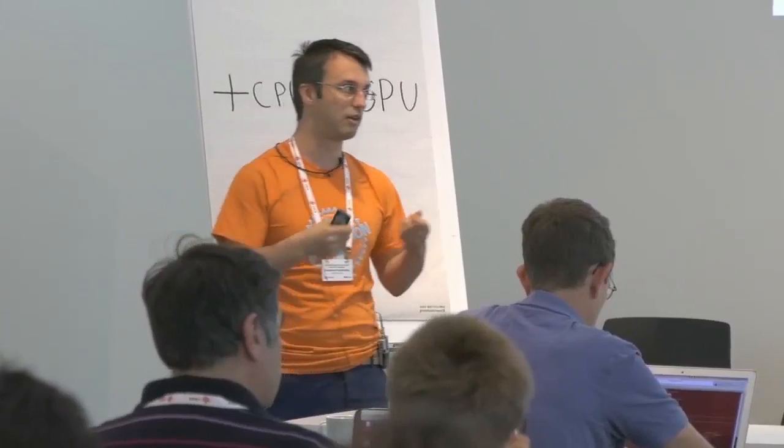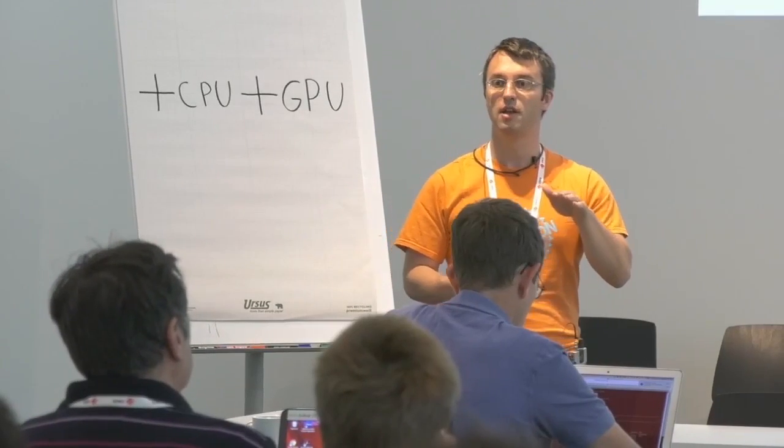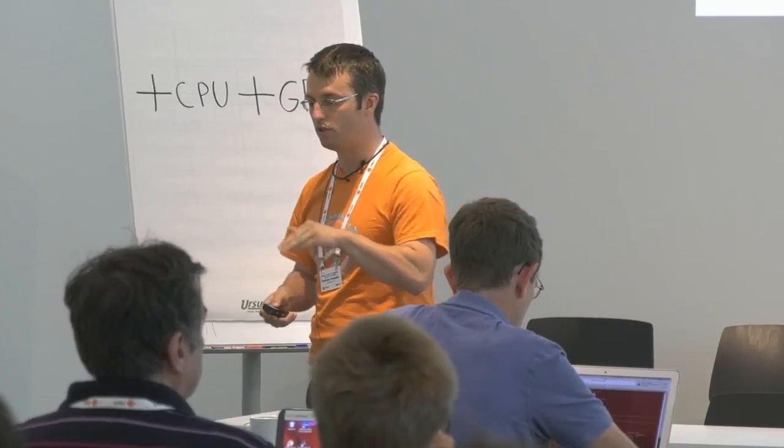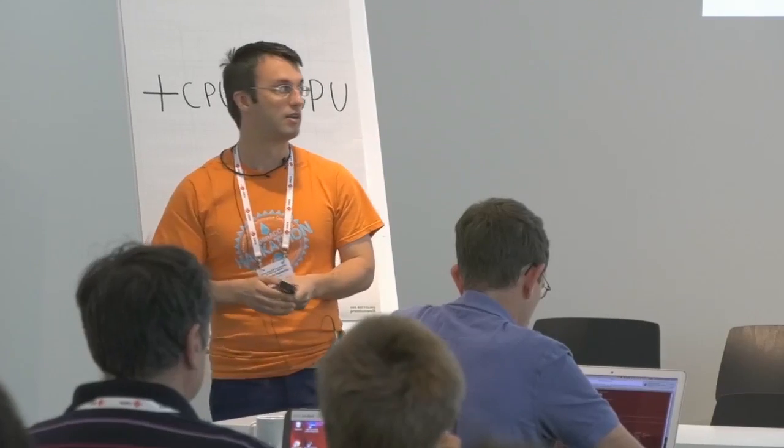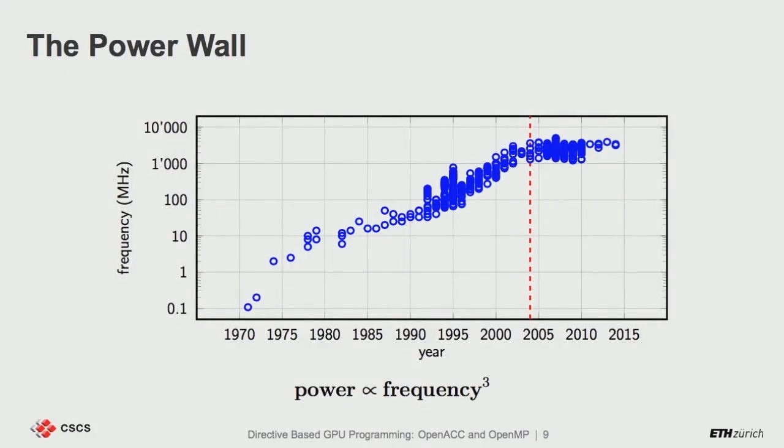This is at the core of each microprocessor. Higher densities gave us the opportunity to have deeper pipelines. For example, the NetBurst microarchitecture has around 30 stages, so each instruction passed through 30 stages. That has the good thing that we could increase the frequency so much, but it had other negative aspects as well, which I'm not going to go through now.